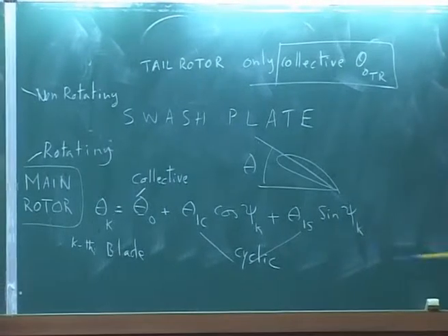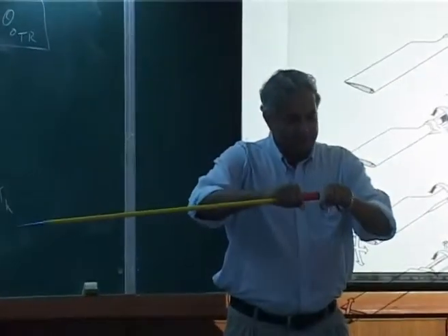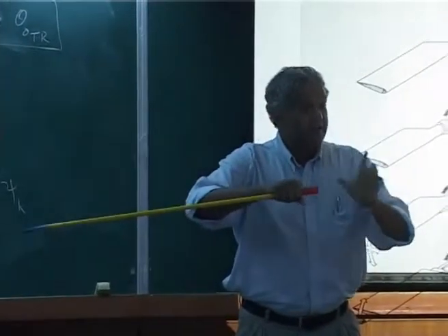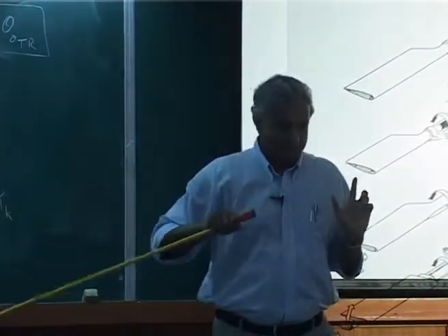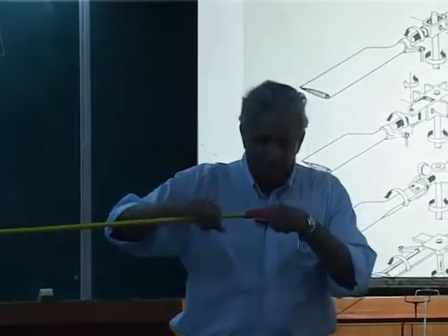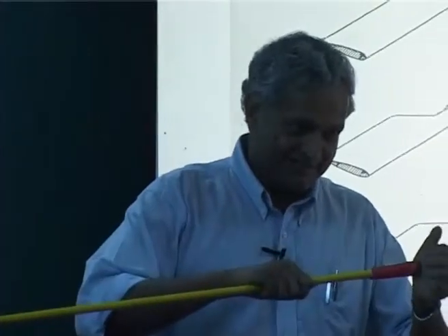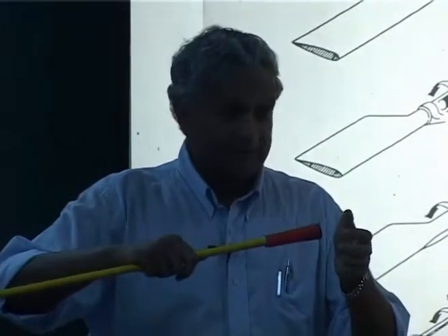That means, if I rigidly attach to the hub, I cannot change the pitch angle. That means, I should have a pitch bearing which will change the pitch angle of the blade. Now, you need these 2. You must attach it, the pitch bearing should be there, but you may or may not have a hinge.